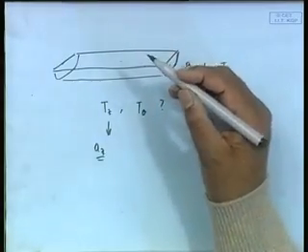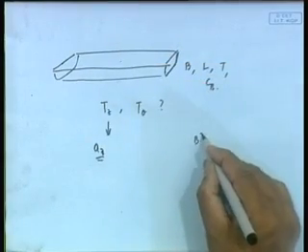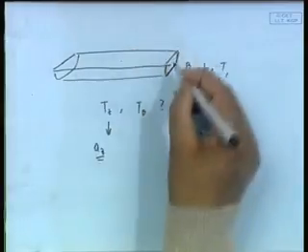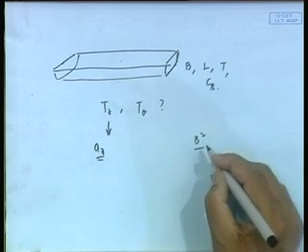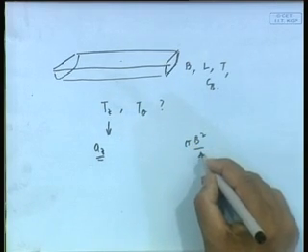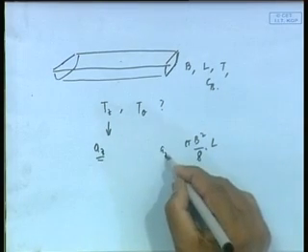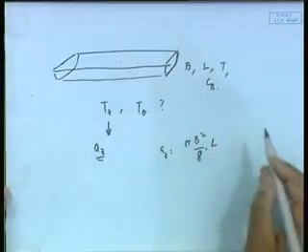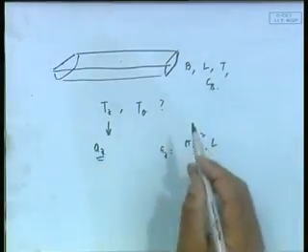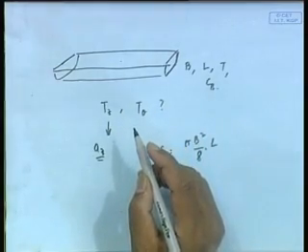Well, I said when nothing is there, simply take this sectional added mass to be pi B square by 8, and this case is very simple because it is uniform cross section and B is constant throughout. So, I have pi B square by 8 into L becomes Az. You understand the sectional added mass is pi B square by 8, integrated along length is L. That is one part. What is my added moment of inertia and moment of inertia?